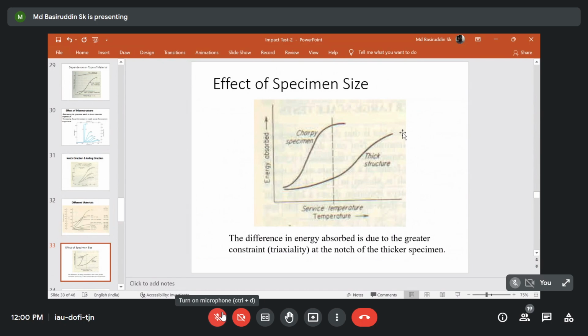considering the high thickness of the material, and we can use lots of material. Okay, and then we can do that test. But for the Charpy impact test, we can readily do that. Yes, but that particular test result is not a material property. Roughly we can assess the material, roughly we can judge the material, but for actual case conditions, we need to go for other testing processes.